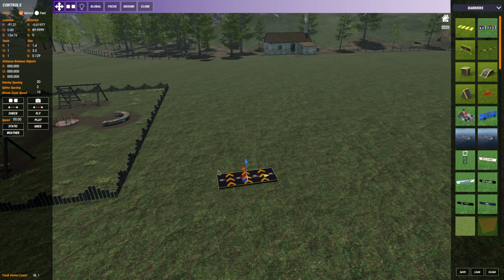So now that this is placed in the bottom left, we want to kind of redefine the coordinate system. So this is at 0, 0, 0. You can see right now it's at a different location, like at 90, 154. To reset this, I'm going to have this selected and do Shift Z. Now you can see if I click off of it and click again, this is at 0, 0, 0. So everything else I do is going to be in relation to this.